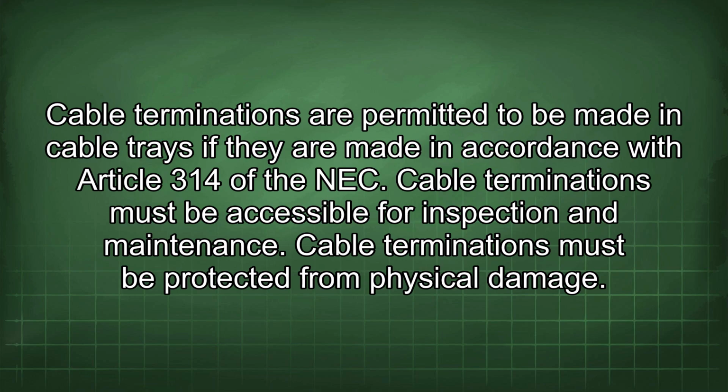Cable terminations are permitted to be made in cable trays if they are made in accordance with Article 314 of the NEC. Cable terminations must be accessible for inspection and maintenance. Cable terminations must be protected from physical damage.